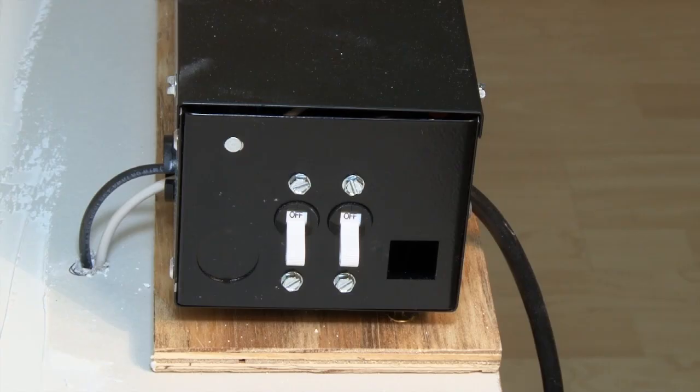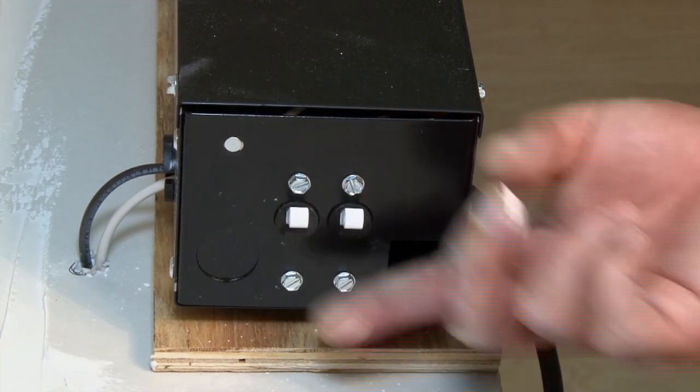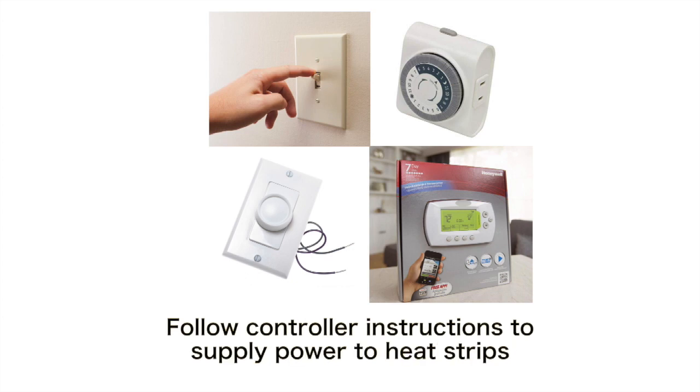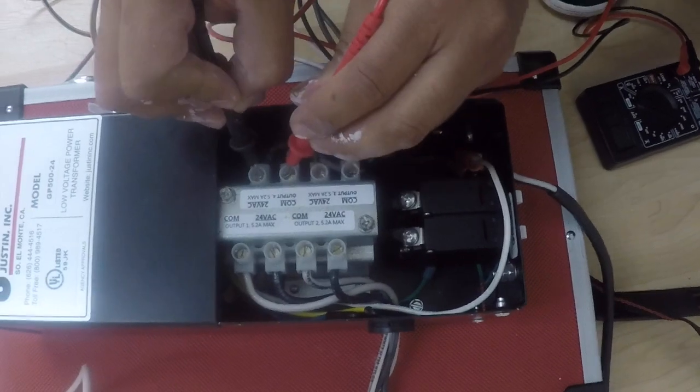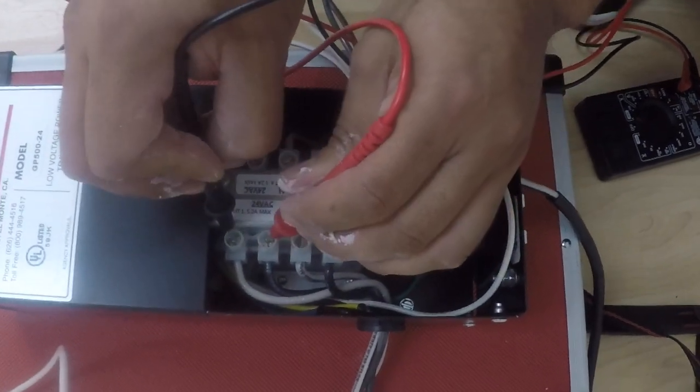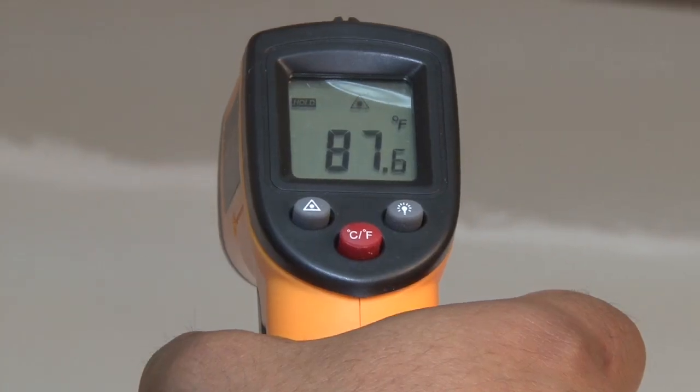Restore power with the building's relevant circuit breakers. After restoring power, flip the transformer switch to the on position. Follow the instructions included with controller to supply power to heat strips. Check for voltage readings from terminal load terminals to ensure voltage is being supplied to heater strips. Use thermometer gun to register a temperature increase from heater strip placement.